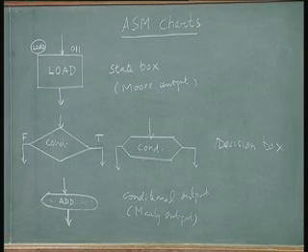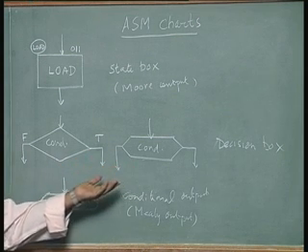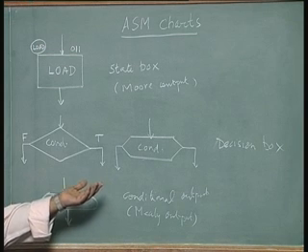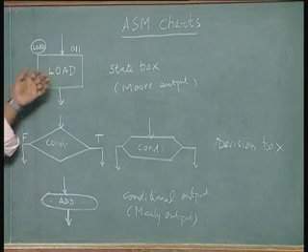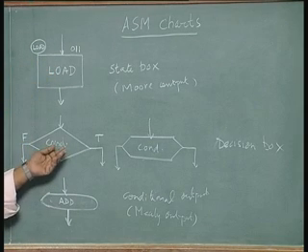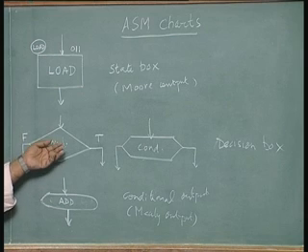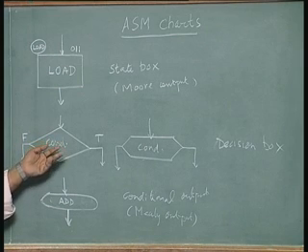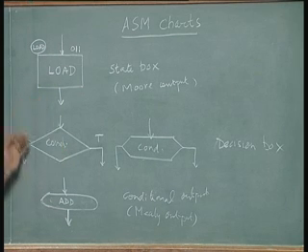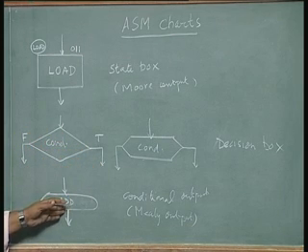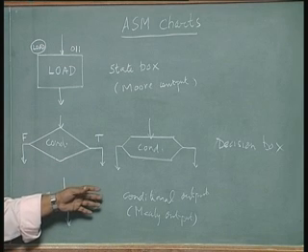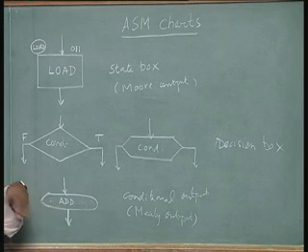So, these are three simple boxes, that is all you can. So, you can draw any algorithmic state machine by what is the state in which the circuit is, what is the signal that is to be tested at that time and conditions that will be tested in that state, what will happen if the condition is true, what will happen if the condition is false, and if the condition is true or false it goes to the respective next state. In so doing it may produce an extra output called conditional output, or sometimes it may not produce an extra output called conditional output. So, this is all there is to it in any algorithmic state machine.